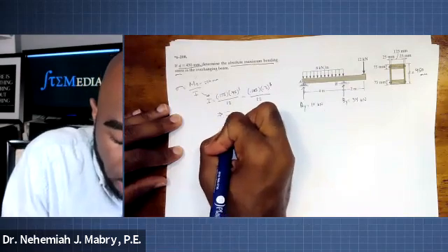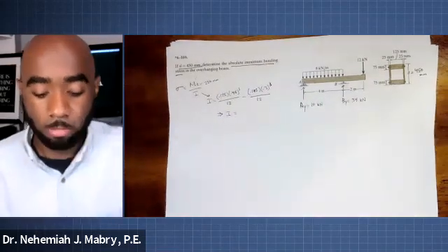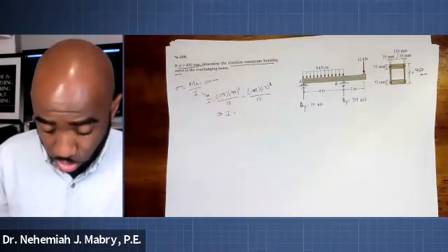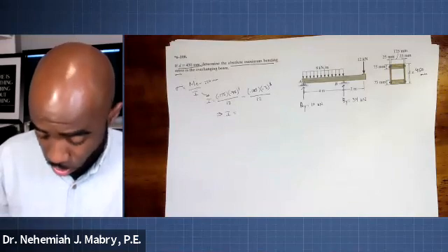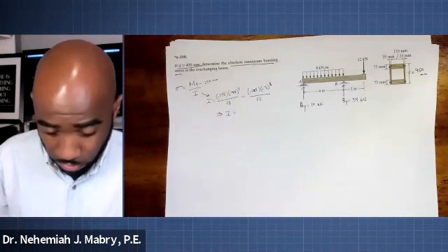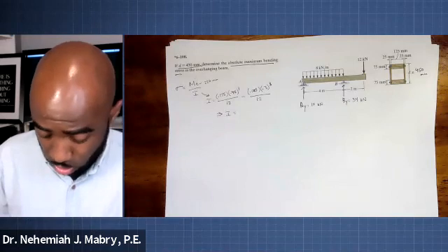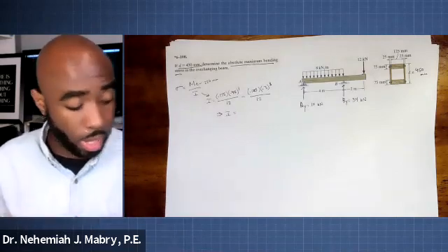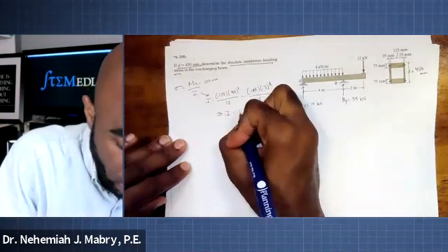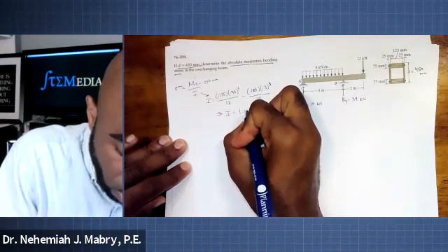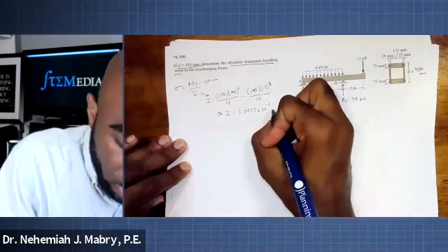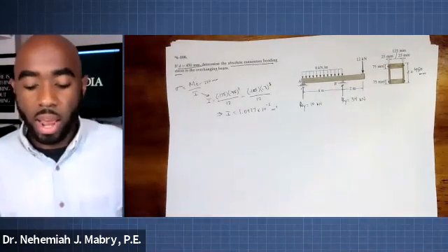So I, right off the bat, we can calculate. You all run it with me so we can make sure we are together. Nobody's fat-fingering the calculator. 0.175 times 0.45 cubed over 12 minus 0.125 times 0.3 cubed over 12. Okay, cool. So we'll write this as 1.0477 times 10 to the negative 3 meters to the fourth. That's our I there.